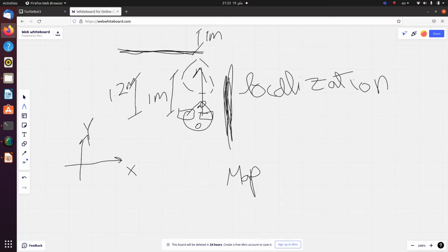And the reading of the LIDAR itself has some noise embedded into it, but the noise of the LIDAR is quite small because we call this sensor an update sensor. Update sensors or update measurements have a high level of accuracy, but they have lower frequencies. Like I get an update every lengthy period of time compared to an IMU.